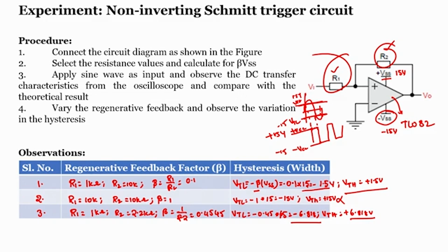If I want to design this using a comparator, it is not possible. With a comparator I can only put one threshold, either at 50 or at 70. If it is a comparator and I set it at 70, when the input temperature is lower than 70 it will switch on, and if it is greater than 70 it will switch off. But in this case it is not like that. When the temperature is lower than 50 degrees, the heater will switch on, and when the temperature is greater than 70, the heater switches off.